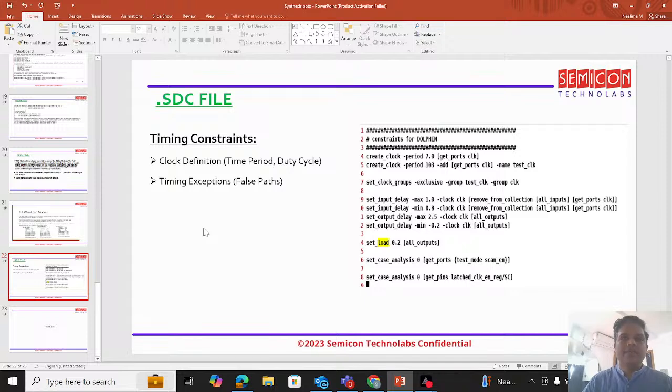So many other factors which we provide, even some of the generated clocks, right, which has to be defined. So all those things will be entering into synthesis loop through the synthesis script, and finally when we dump out the SDC file as output of synthesis, at that time we will have all these constraints defined in the SDC file, functional SDC file, which will become as input to the physical design.